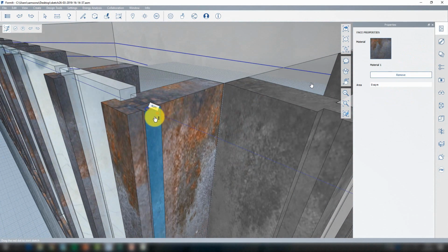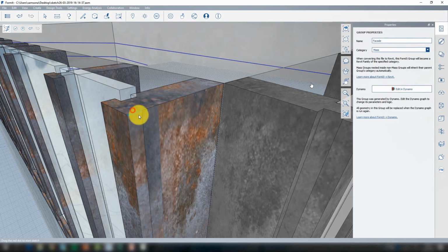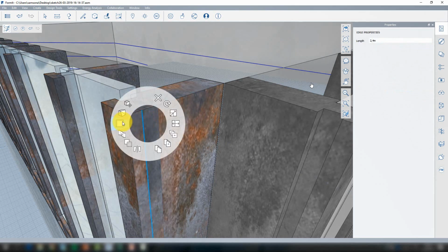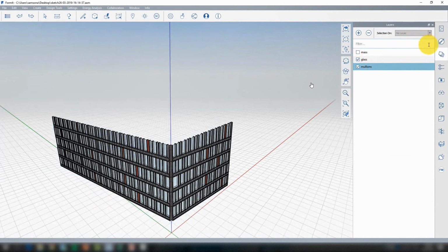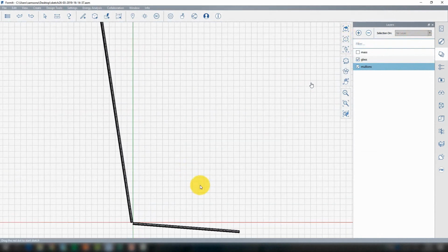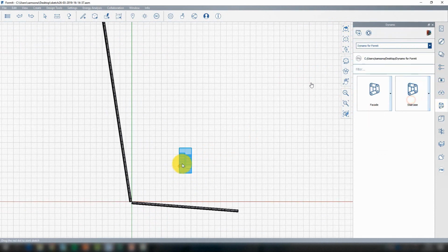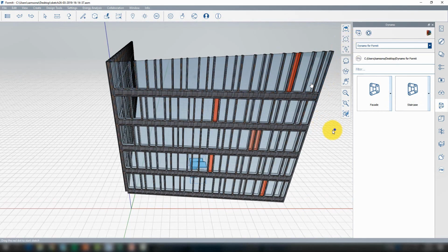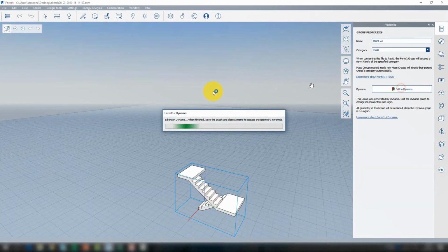And of course, I can also control it. Once I have my geometry generated by Dynamo in FormIt, I still have access to it. But if I would like to change this inclined facade with Dynamo, then by exploding it I'm losing the associativity with the Dynamo script. So the fact that it's parametric is lost when you explode it.